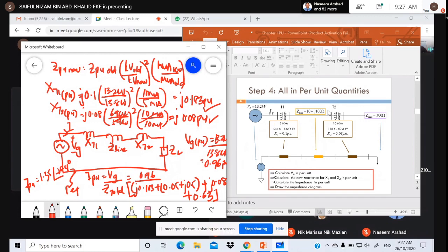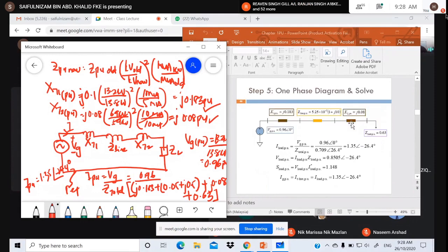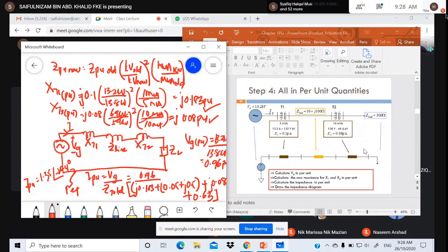The per unit current is the same, since in per unit representation, remember we already removed the coupling circuit of the transformer. There is no longer a coupling circuit. It becomes a single impedance, XT1 here, and also the same for XT2. So do you get this per unit current? The answer is correct. Yes. Now, after getting this per unit current, what's next?